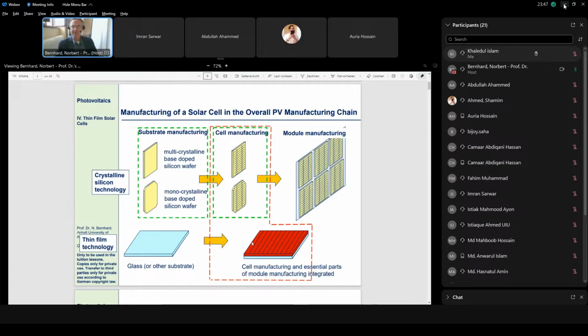That means in principle there's sufficient energy that the electrons are thermally activated above this barrier, and although this barrier is here, they can reach their contact. And I should also say, the cadmium sulfide layer here is very thin. It's less than 50 nanometers. So that's less than a thousandth of the thickness or diameter of a human hair.